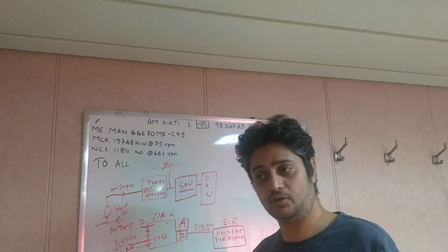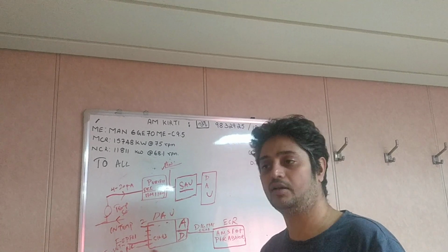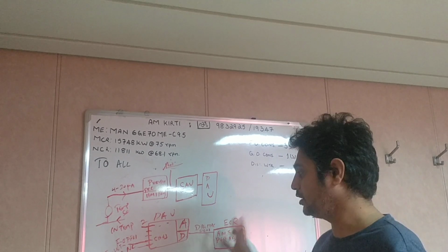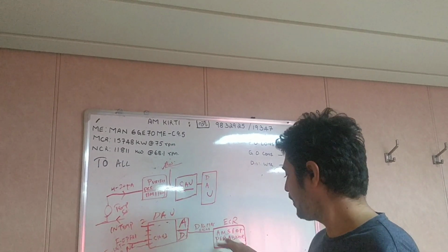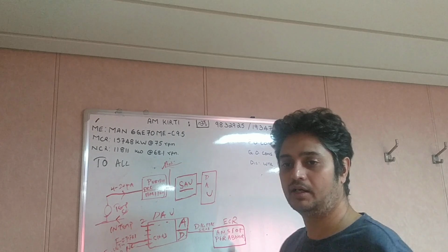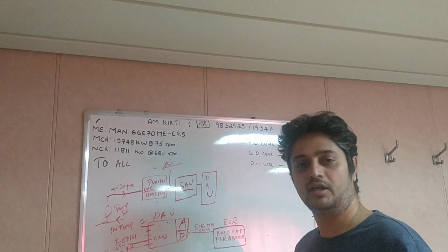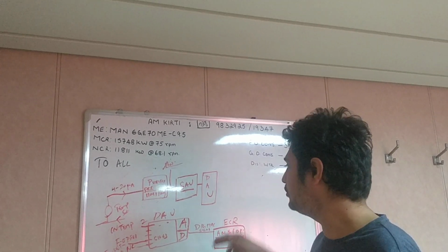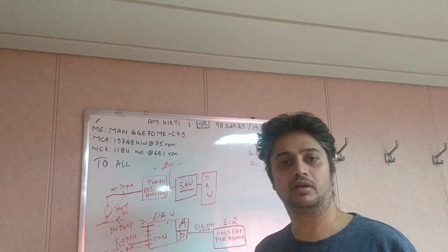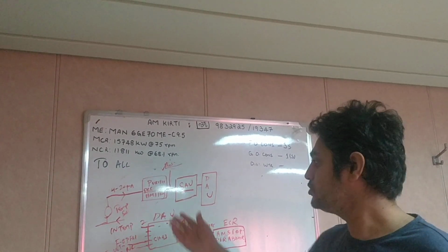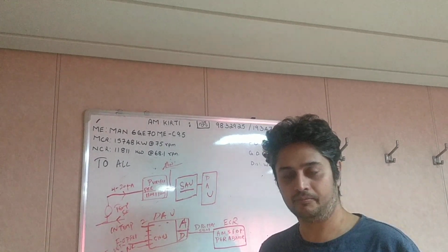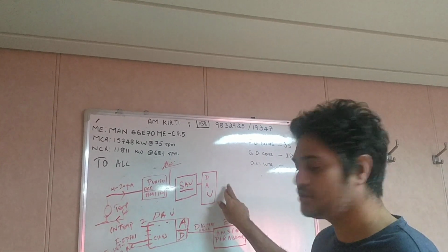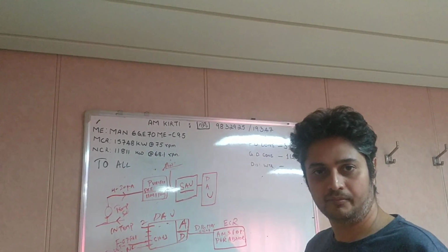If the AMS maker has configured his AMS software to tell that if this port activates, you give an alarm, it could be inlet temperature low, but mostly it will be a common alarm. Then once the common alarm triggers, we will go and see in the purifier panel what the alarm was, which will be displayed there in the purifier. I hope you got an idea. The digital acquisition unit is where all the things are happening.